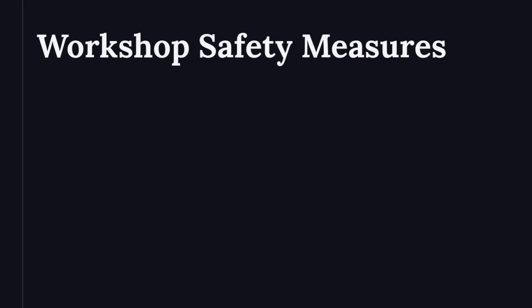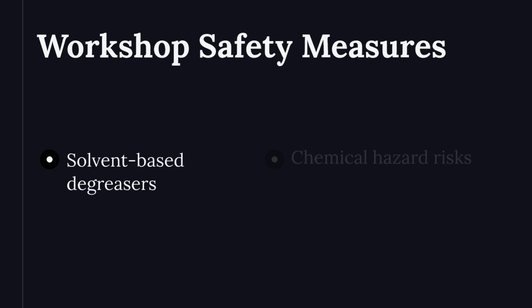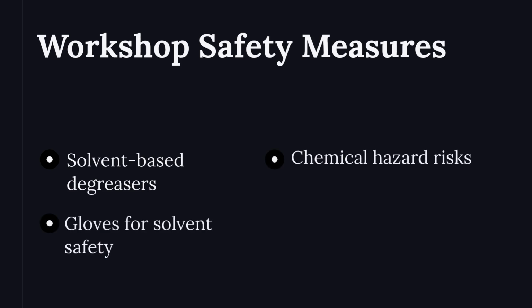A workshop uses solvent-based degreasers. The risk assessment identifies chemical and mechanical hazards. Gloves must resist solvents and protect against cuts. Consider combining different gloves for optimal protection. Ensure dexterity is maintained with the chosen combination.